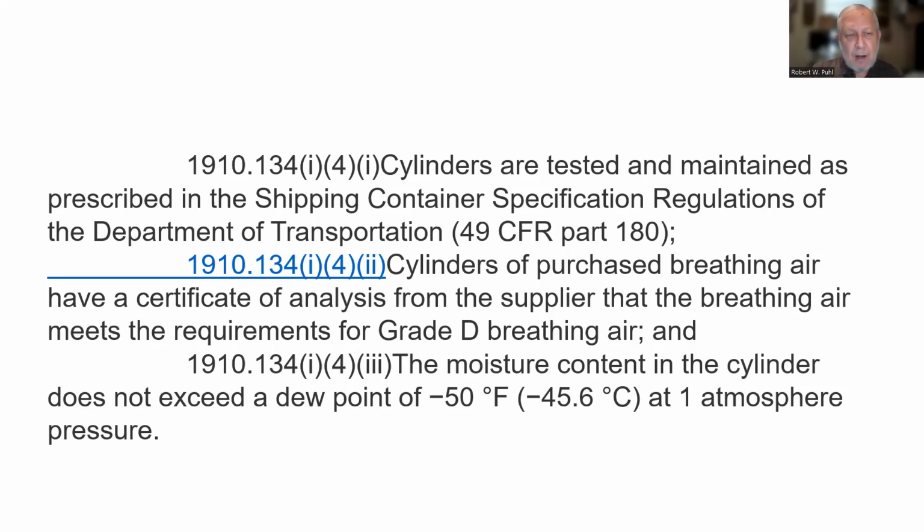Cylinders of purchased breathing air have a certificate of analysis from the supplier, and the breathing air meets the requirements of grade D breathing air, and the moisture content in the cylinder does not exceed a dew point of minus 50 degrees Fahrenheit at 1 atmospheric pressure.